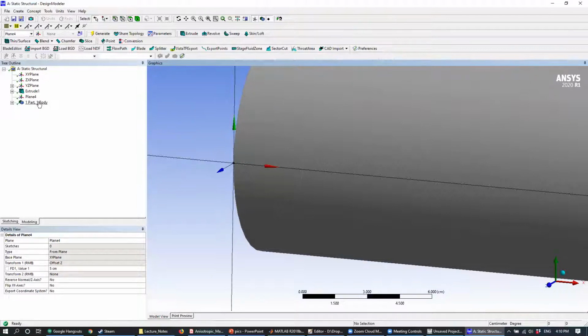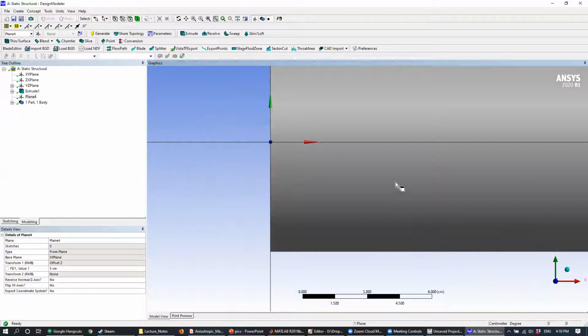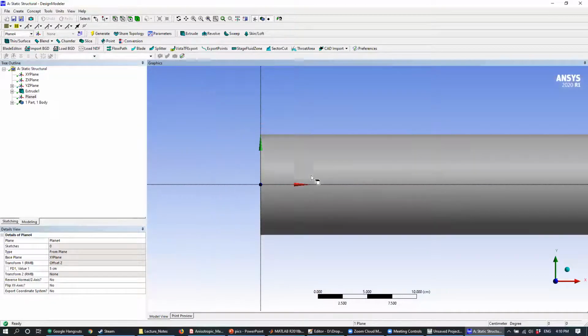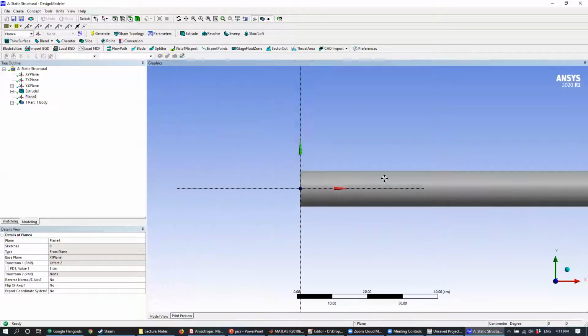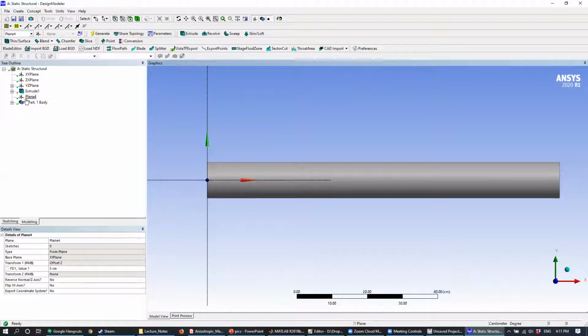Okay. So then let's go ahead and start sketching. The next step is we need to sketch the shapes that we want to project, because in this plane we can draw shapes. Let's go ahead and center it on the Z-axis so that we can see what's going on here. Let's zoom out a bit, just so we can see. Once we've created our plane, let's left-click it. And of course, you can give this a new name to be more descriptive. So let's call this projecting plane.